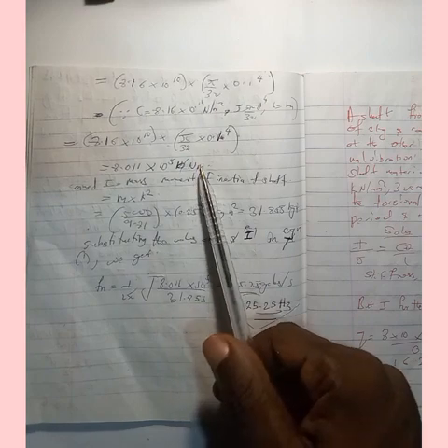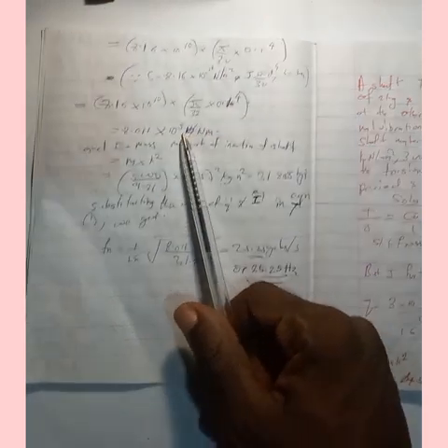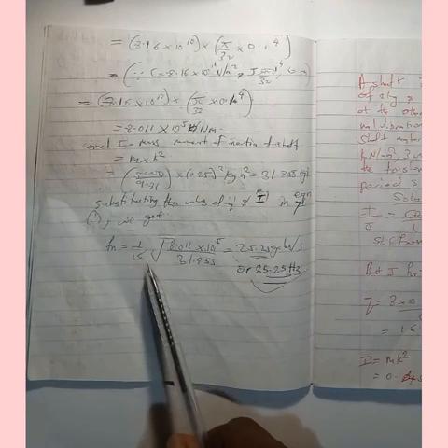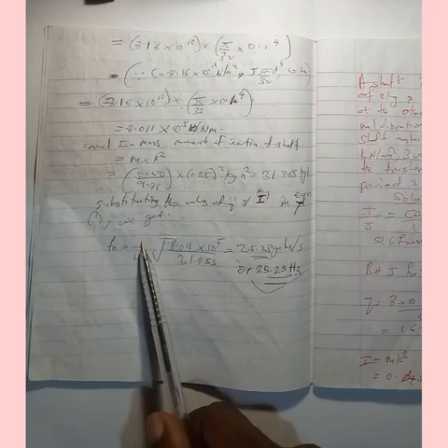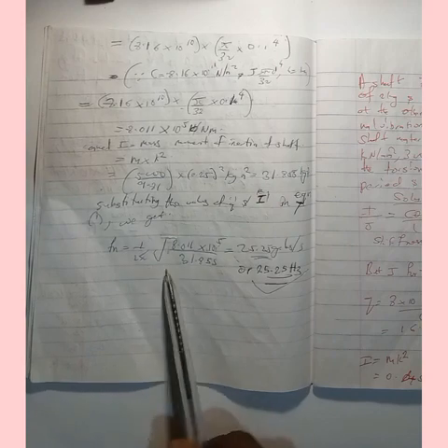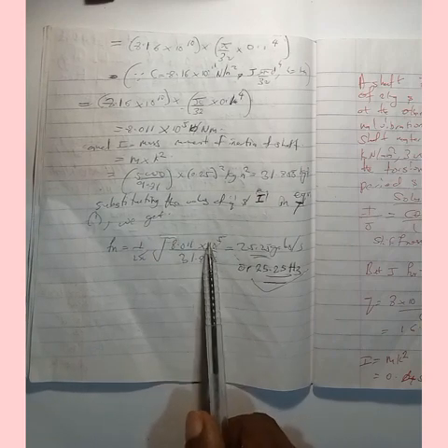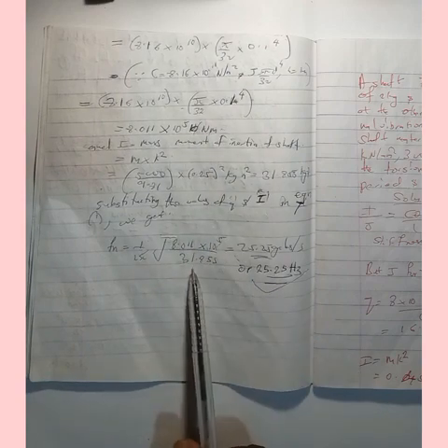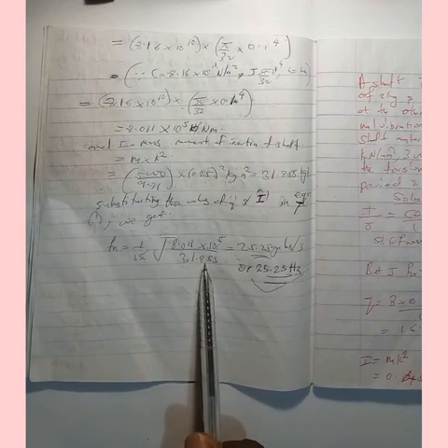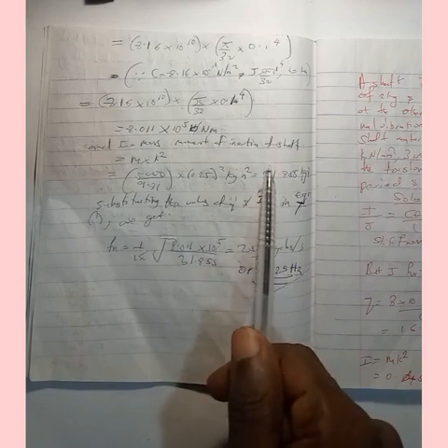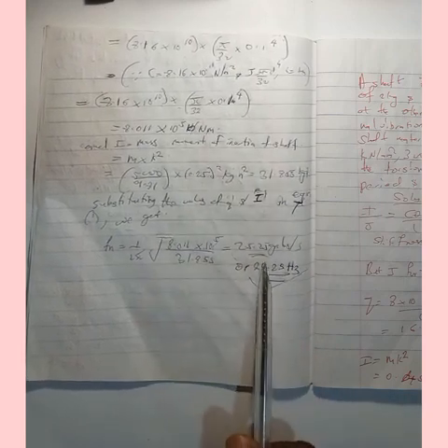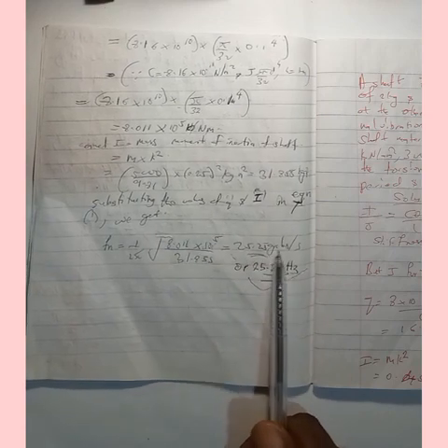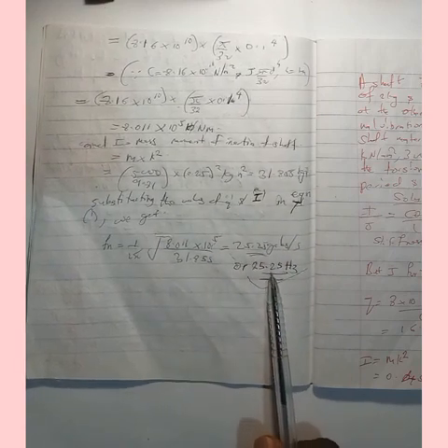We can now substitute these values into the formula for frequency of torsional vibration. So f n equals 1 over 2 pi square root of q, which we've gotten as 8.011 multiplied by 10 raised to power 5, over 31.855, which is our I, and eventually the frequency gives us 25.25 cycles per second.